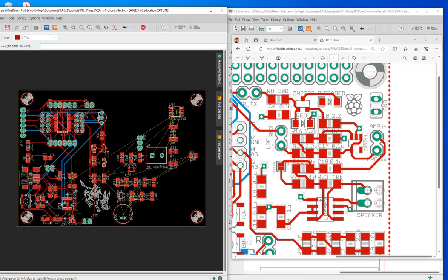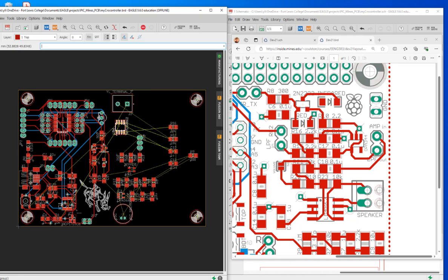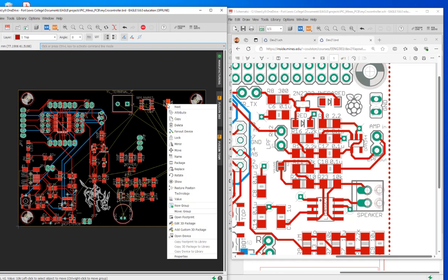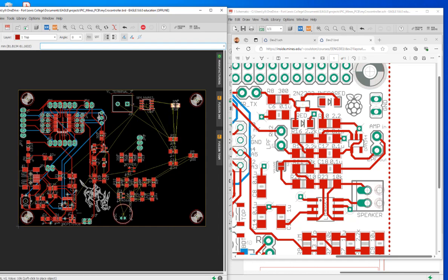So it seems like you can definitely place this guy here. Terminals are always at the edge, keep in mind, okay, at the edge. And just look at the connections. I believe if I do this, the router will be very happy. Let's just do this. Okay, I'll just place next to it. And then you have a couple of resistors. Just place them in the location that you think is gonna make the router's life easier.